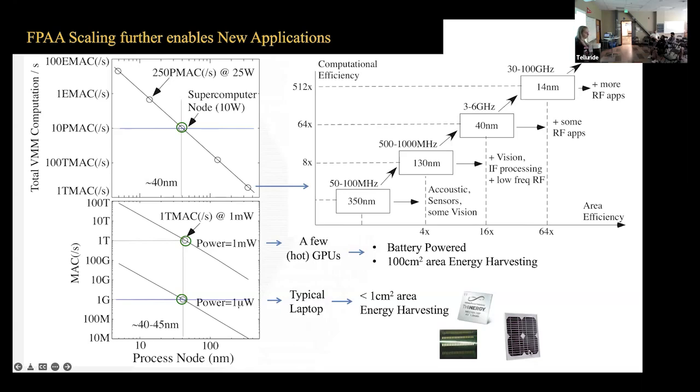For example, we're at 40 nanometer. We know that we can definitely get 4, 5, 6 gigahertz signals through there, with 1 to 2, 3 dB loss through the path. And you can actually get that through the routing fabric, and we know that works. So as soon as you can say, I can actually put something from 0 to say 4 gigahertz into the routing fabric, that opens up a whole set of questions. Remember, we can also do the vector matrix multiplication in the routing fabric. So now the game gets rather fun in terms of what you could do there.